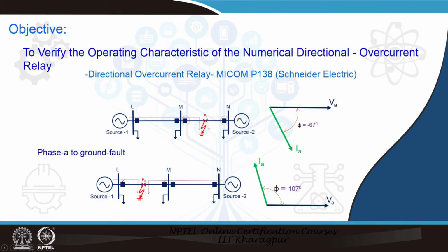So, that leads to the situation of discrimination; the angle between the voltage and current is indicative of the direction of fault. For that perspective, as usual many times in the distribution system and other systems, the overcurrent relay plus the directional relay are being used. So, we call these things overcurrent directional relaying. In that aspect, both overcurrent and direction are to be satisfied for the trip decision.